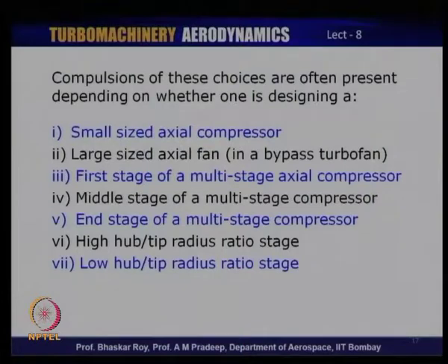I mentioned that geometry is an important parameter. Let us look at some of those issues. Now, if you have a blade which is, let us say, a small sized axial compressor, that will impact the design, or it will tend to take the design in a different direction, compared to a blade which is a large sized axial fan, as one can see in a bypass turbofan.